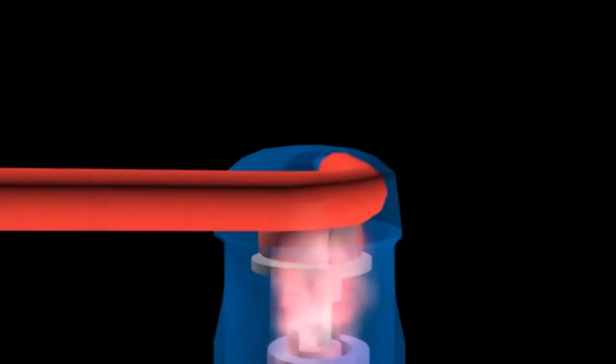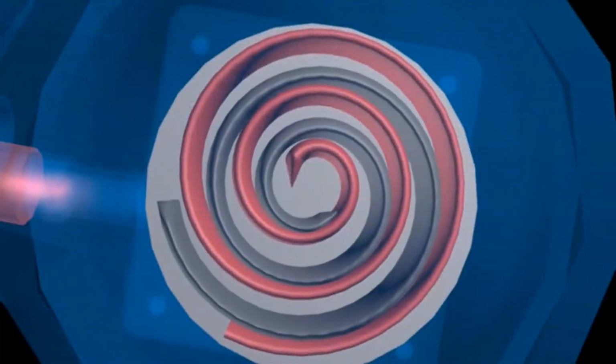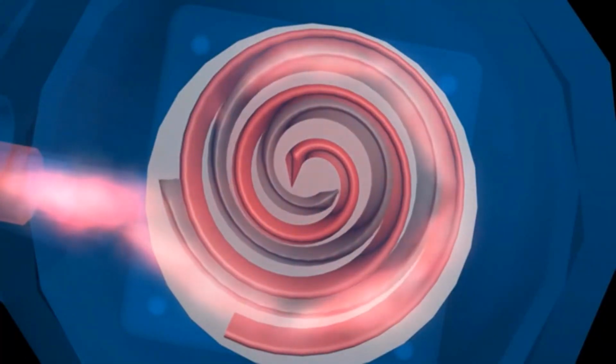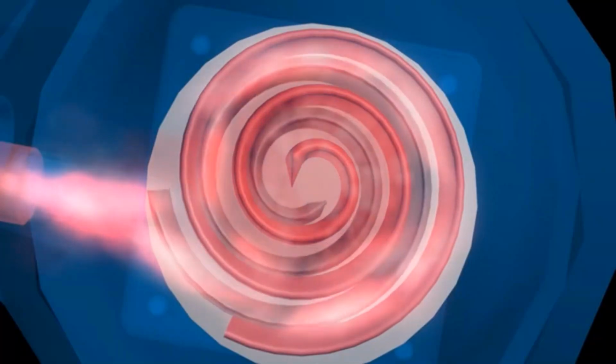The type of compressor used is the scroll hermetic type. A scroll compressor works as follows: gas at low pressure and temperature enters the suction line and goes into the compressor. The low pressure and temperature gas is pressurized by the scroll compressor to high pressure and temperature gas. The high pressure and temperature gas is then passed through the discharge line and goes into the condenser.